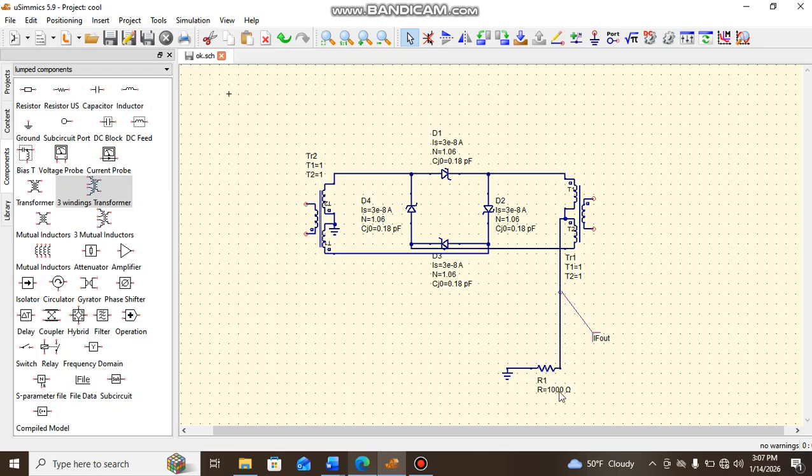I could probably change it and see how that changes my impedance for the RF input, so that maybe I need to change the matching network to my mixer, to the input of the RF mixer.